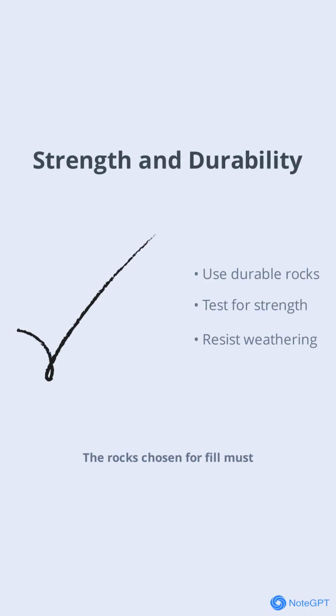Rocks chosen for fill must be strong and resistant to weathering. Using rocks that are easily broken down by wind, water, or temperature changes can compromise the stability of the structure. Therefore, it's important to select rocks that have been tested for strength and durability. This ensures that the fill will maintain its integrity over time, even under heavy loads or in harsh environmental conditions.